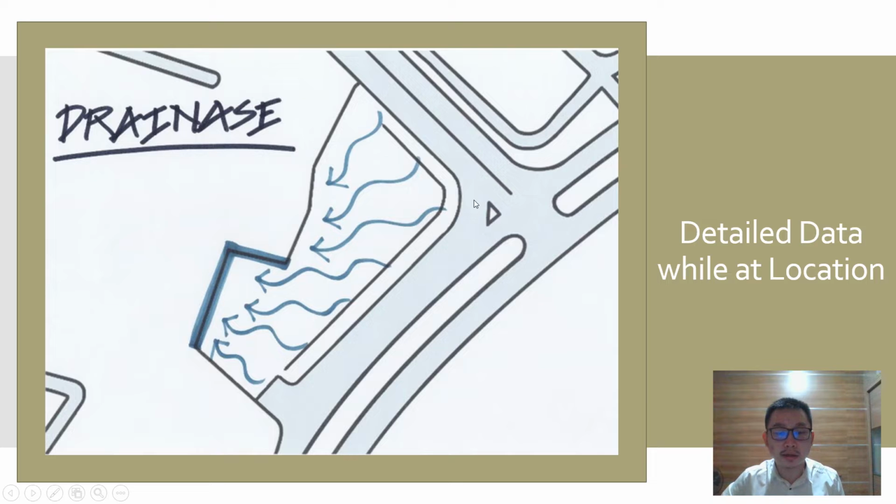The drainage part. Due to the depth differences in the site, we just try using its current condition to function as an external sewer, as we see here. This is because it is way too low to connect the sewer to the city's main sewer, whose location is 1 to 1.5 meters deep, measured from the city's sidewalk. As marked here, sorry, I did not draw the details of the sidewalk.